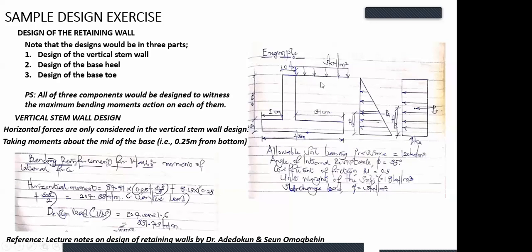You know that your earth material is this triangle, right? The other one that will have lateral pressure is your surcharge. And your surcharge is rectangular in nature, not triangular. So the centroid of a rectangle is at the midpoint of that rectangle. So it's supposed to be h/2. If you notice, for my surcharge I've been using h/2, but now the h is 5.5, no more 6. That's why I have 5.5/2 plus 0.25, which is the midpoint of this base. Is that clear, sir? Yeah. Thank you.